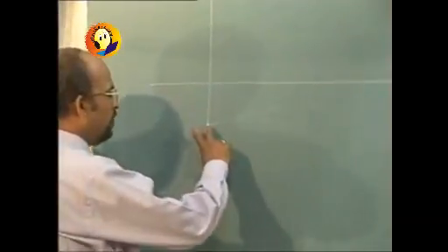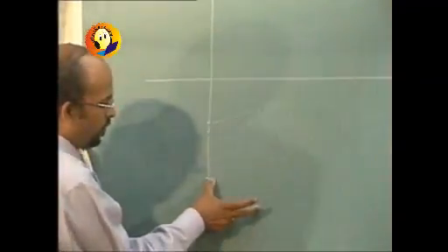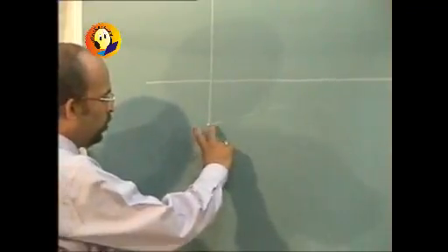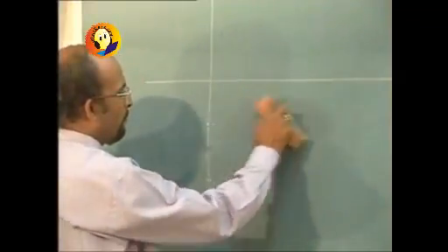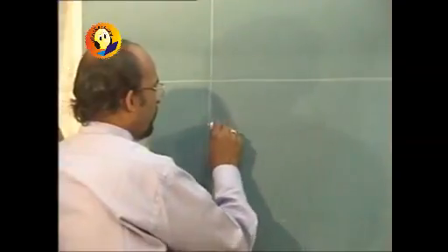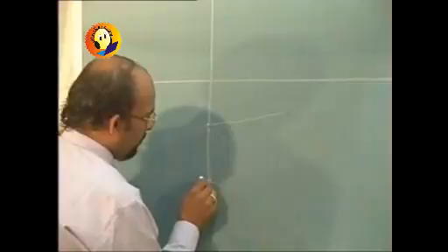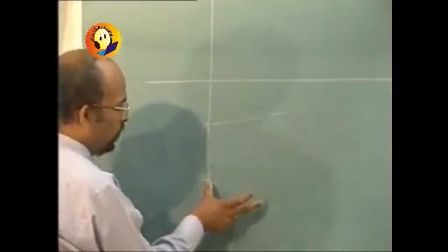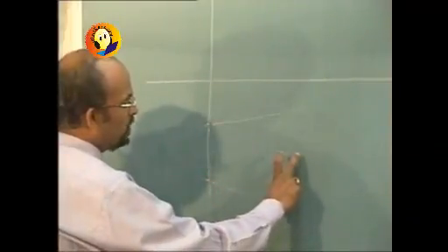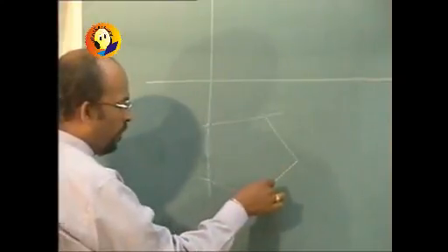And then you can mark the sides as 30 mm on both the angles. So you take distance equal to 30 and mark on each one of them, and from those 2 points you can cut the arc to complete the pentagon.